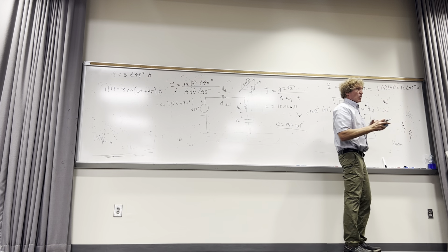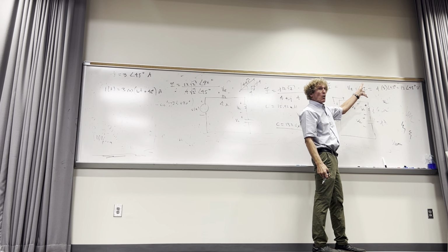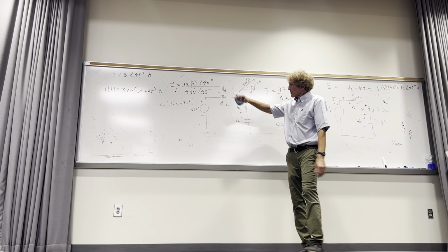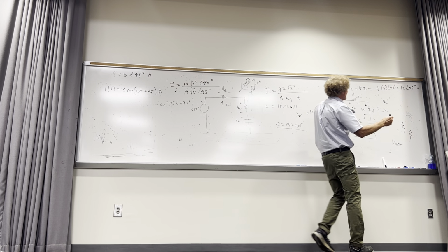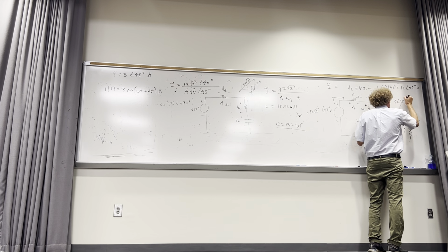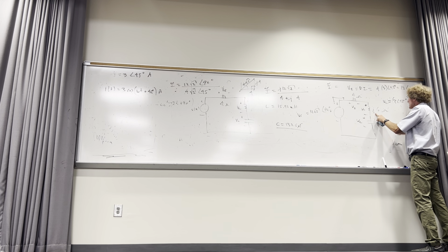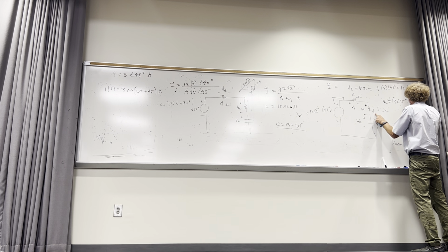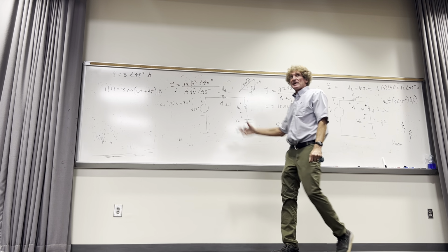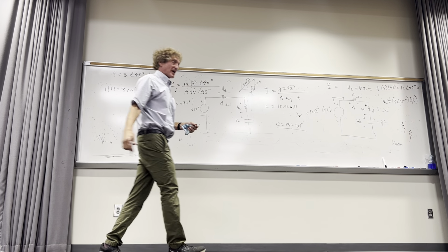Anyway, what is this voltage going to be, VL, plus to minus? Well, it's the current going in, 3 at an angle of 45 degrees, times what? J6, right? Take your calculator, see what comes up. J6 ohms. Now, how many know that J6 ohms is 6 at an angle of 90 degrees? Isn't that right? Save yourself some time.